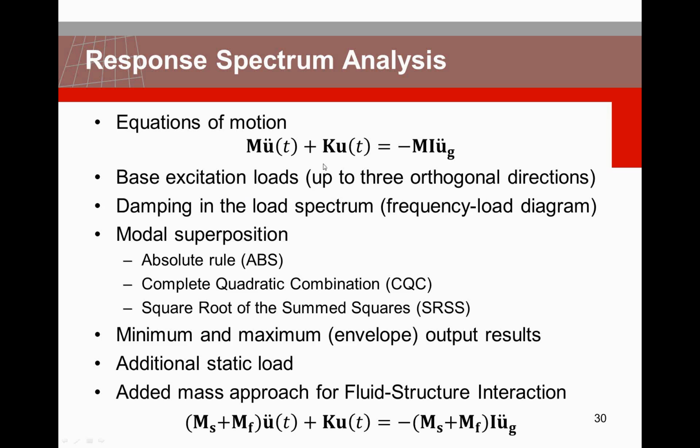Regarding the damping, you see there is no dedicated C matrix here, so you cannot specify, for instance, Rayleigh damping, because it is not used in response spectrum analysis in that way. The damping is in the loading spectrum, in your frequency load diagram. If you look at Eurocode 8, for instance, these diagrams are for a certain damping ratio, for instance 3% or 5% damping. So there is no explicit specification of the damping in the sense of material properties, but it is accounted for in your frequency load diagram.